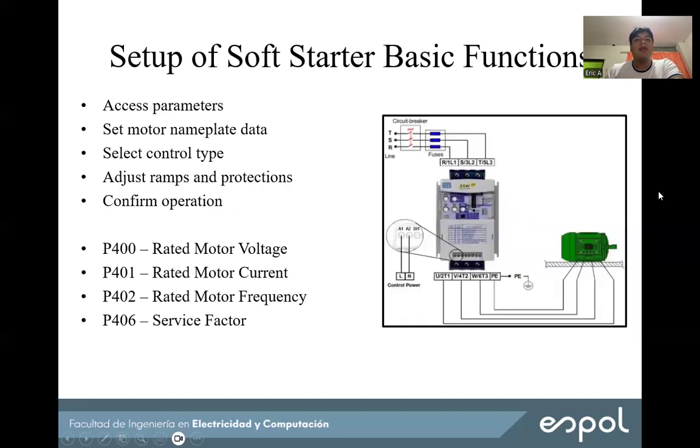First, we set the motor data from the nameplate. We select the control type. We adjust acceleration and deceleration ramps. We set protections. Then we confirm correct operation.